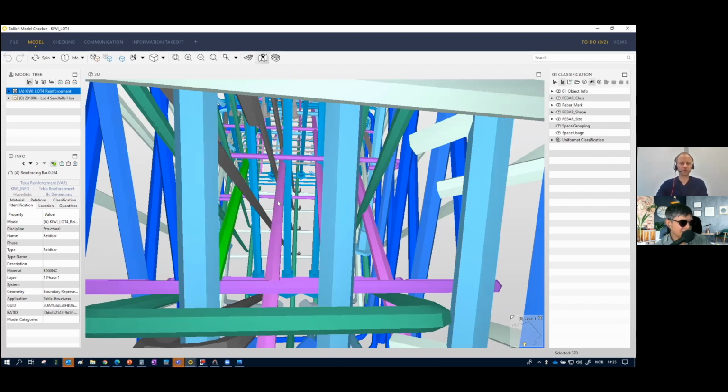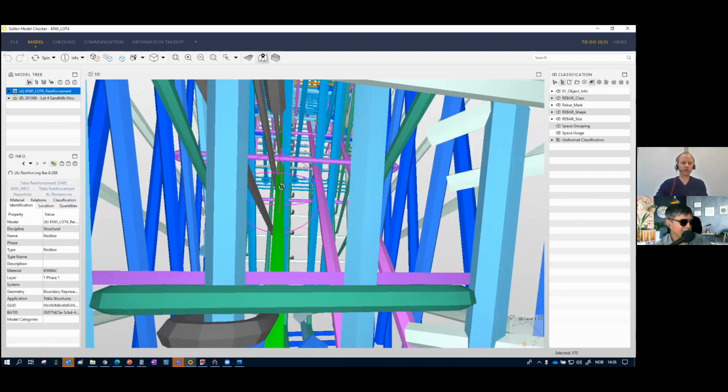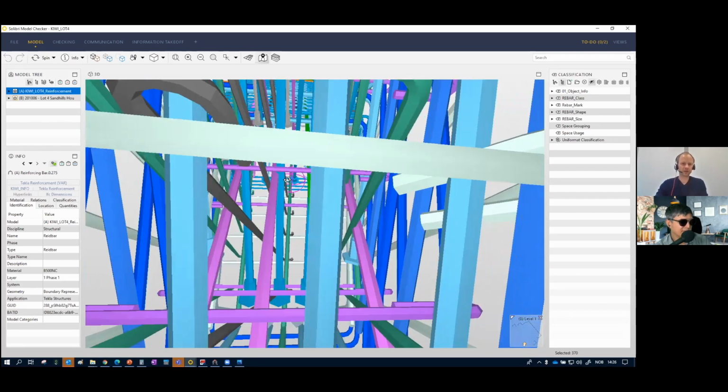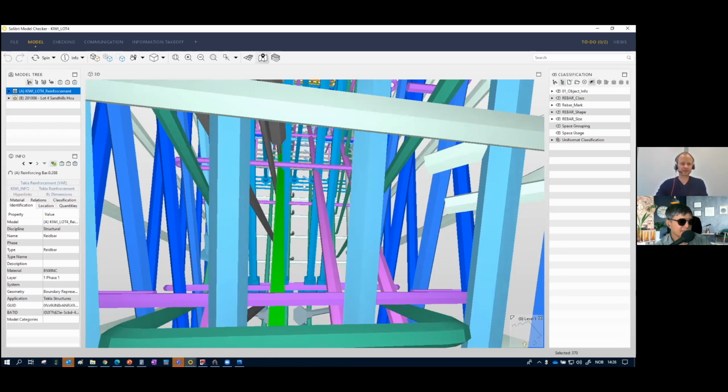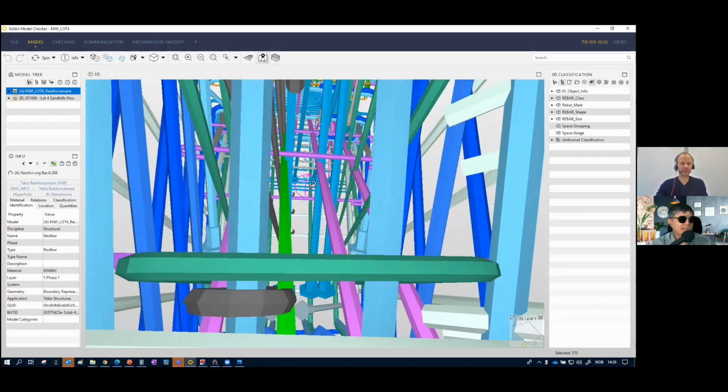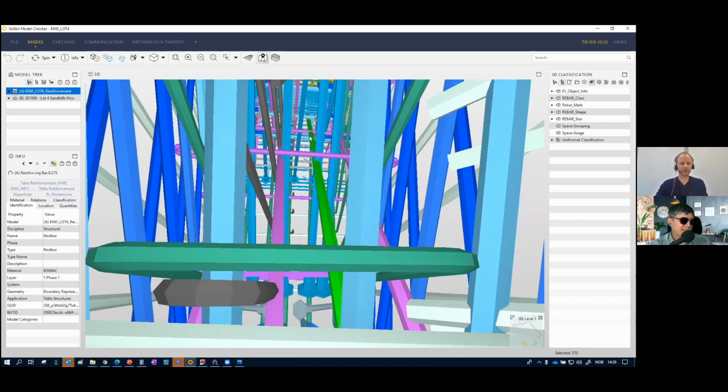You don't want to explode it, so every rebar is unique. So if you can see from your design that clashes are solvable, then allowing small clashes like this is okay, because you can see that if I tilt this a little bit, we will have space.